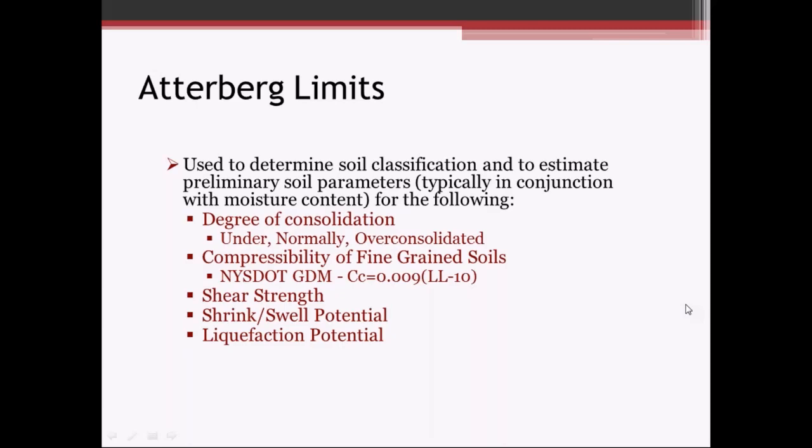As far as liquefaction potential, loose non-plastic silts and sands below the groundwater table are the most susceptible to liquefaction. So we would typically use the Atterberg limits along with the particle size analysis to evaluate liquefaction potential.